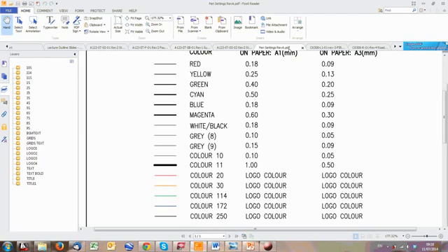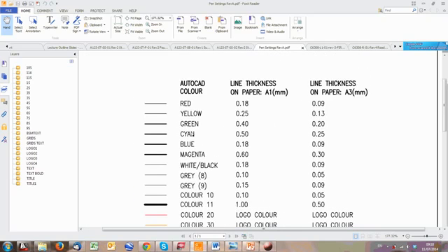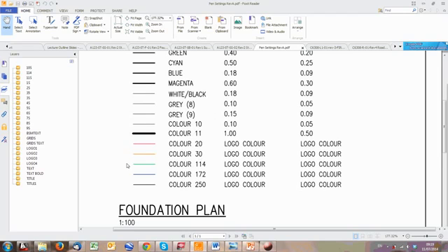I'm just going to go to my pen settings. So you'll see when I create a drawing or PDF from what we were just looking at, red just comes out black, and yellow, and all these colors come out black, but with different thicknesses. And you can use those thicknesses to emphasize or not emphasize certain things. If you want, you can even make them come out in color.